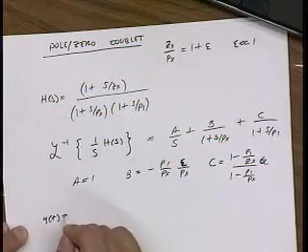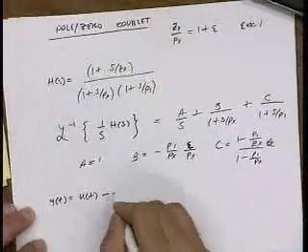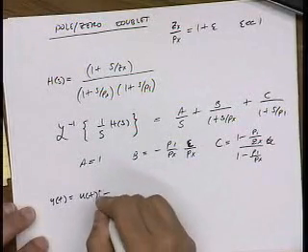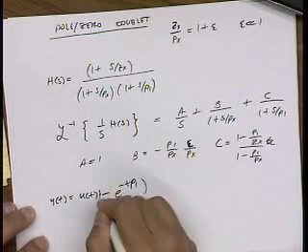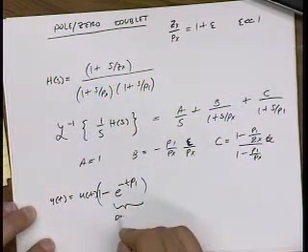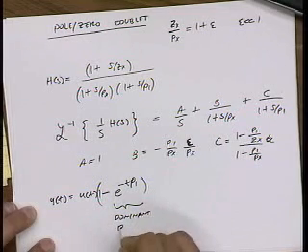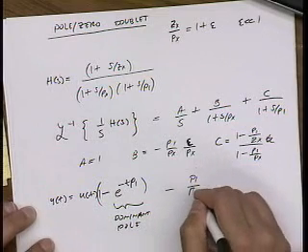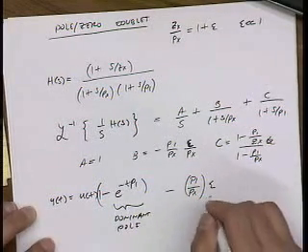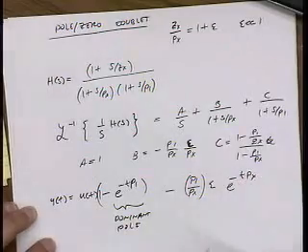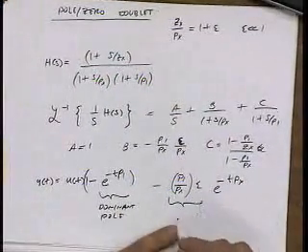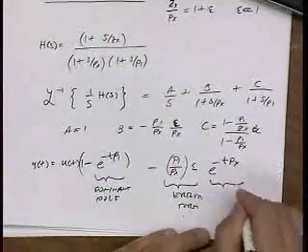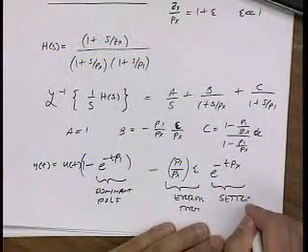All right, so the output response looks something like this. We have our ideal step response. This is the dominant pole response that we've analyzed. And then we get some error term, which I've approximated here, but maybe I should double check this approximation. But the important point is that this is my error term, and then this is my settling time of the error term.